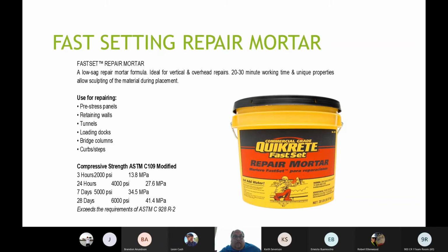Now, one thing to keep in mind too is you're going to usually have the cracks and then they go into hairline cracks. You need to take a crack chaser or something, and grind those cracks out on the hairline side, because you're putting a sanded material into a crack that's a hairline. You're not really going to get any material to fix the crack. The main reason why you do want to fix that crack is you want to make sure that there's no water getting down in there washing out that substrate, making that crack larger, getting it room to grow. That's the important part.